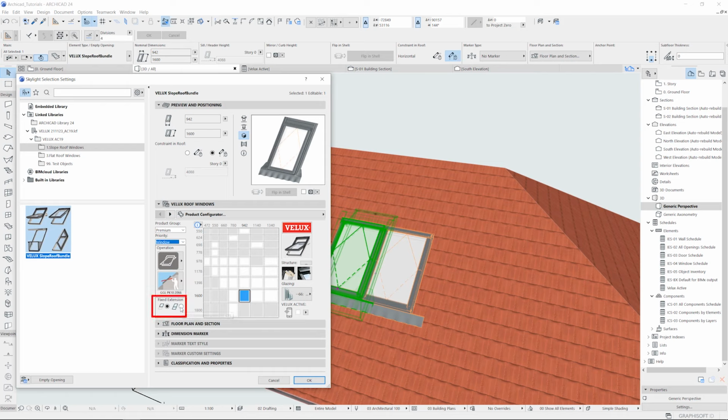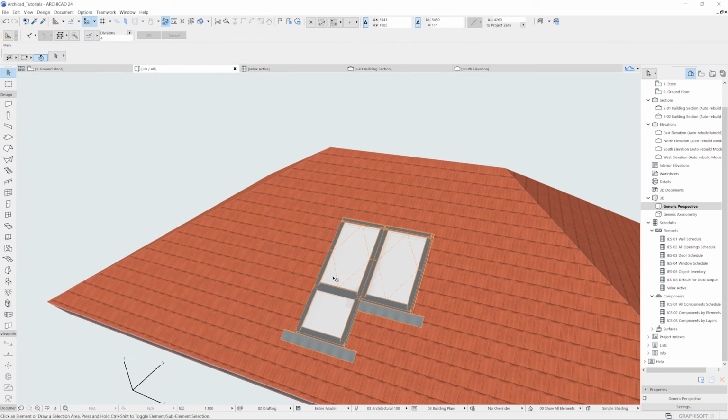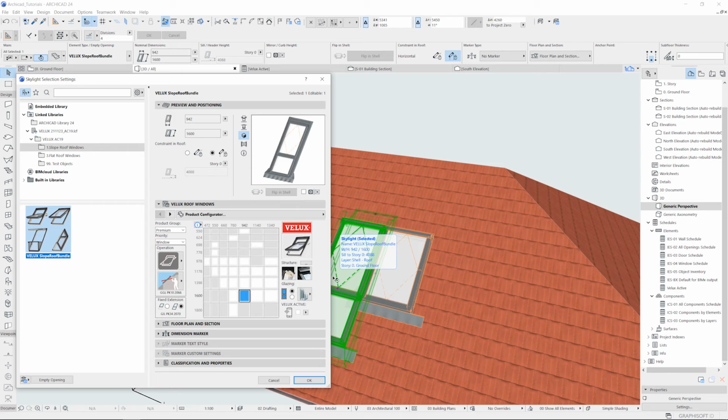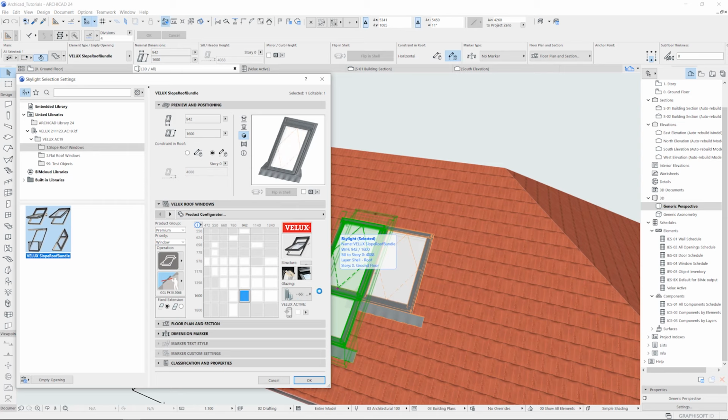Here we can choose to add a fixed extension. This extension is a fixed window, which will be connected below the configured window. Remember to choose a glazing for the extension as well. The VELUX Active selection here will not add any geometry to the project, but add a VELUX Active product to the product schedules. These schedules containing bill of materials will be explained in a later video.